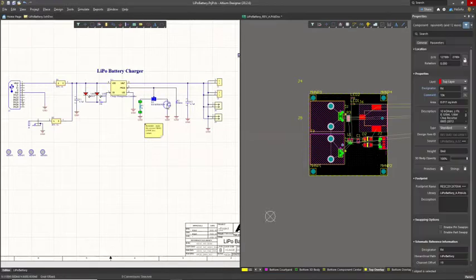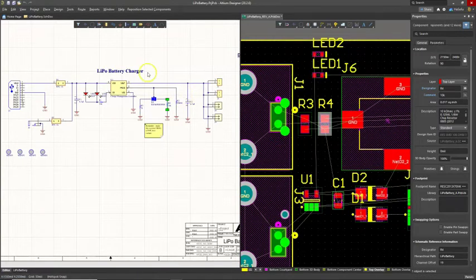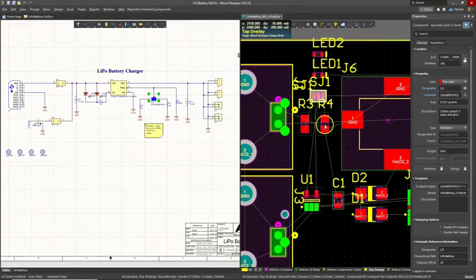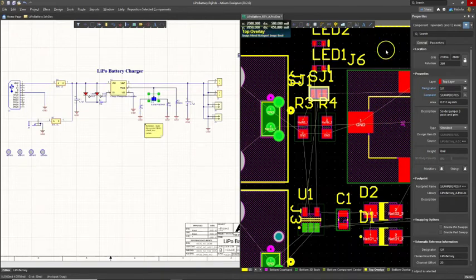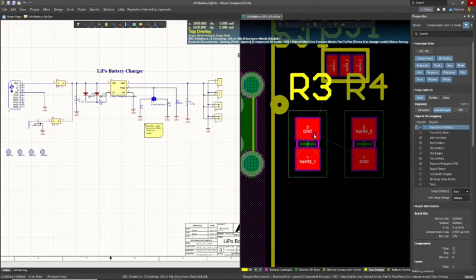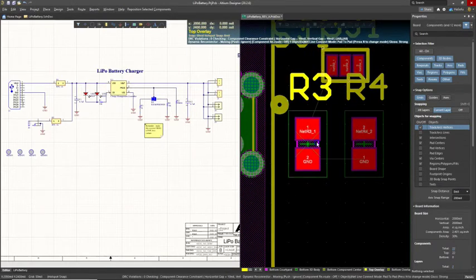But I'll just place them maybe like this. Let's look at the jumper. Alright, that works. Okay. How do I know how to place them? I look at these things called air wires or rat's nest lines, and I want to keep these as short as reasonable. So instead of rotating the part like this, it might be trickier for me to route from the bottom of this to the top of that. It makes the line unnecessarily long, so I'd rotate it.